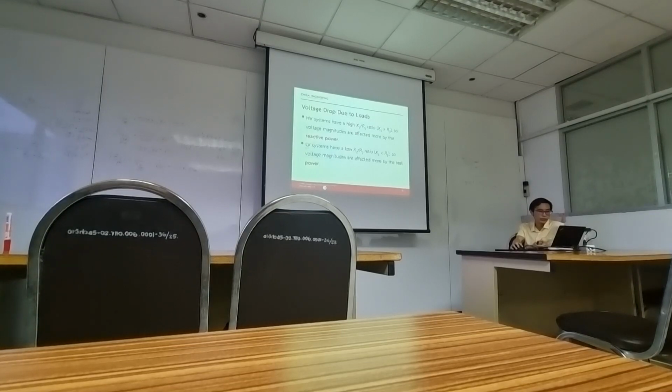But for a low voltage system, the X over R ratio is low. X is smaller than R. The voltage magnitude is affected more by the real power. You can see this equation. If R is large, X is small, PL will have a lot of impact on the voltage magnitude compared to QL.